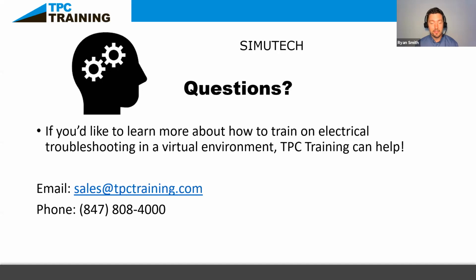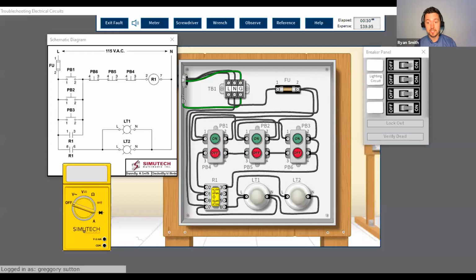I think I can field this question, and definitely help me here, Greg. What is the R1 slash R2 in that schematic we saw earlier? It seems to be an open circuit, but the lights were still turning on. Those were absolutely an open circuit to begin with, or what we call normally open. So what I think we were seeing was normally open contacts that don't allow the current through to the light until they get closed by that relay through the power of the magnetic action of that coil closing them. What you see in the schematic, right there at the bottom, R1, it appears open, and that's absolutely true.